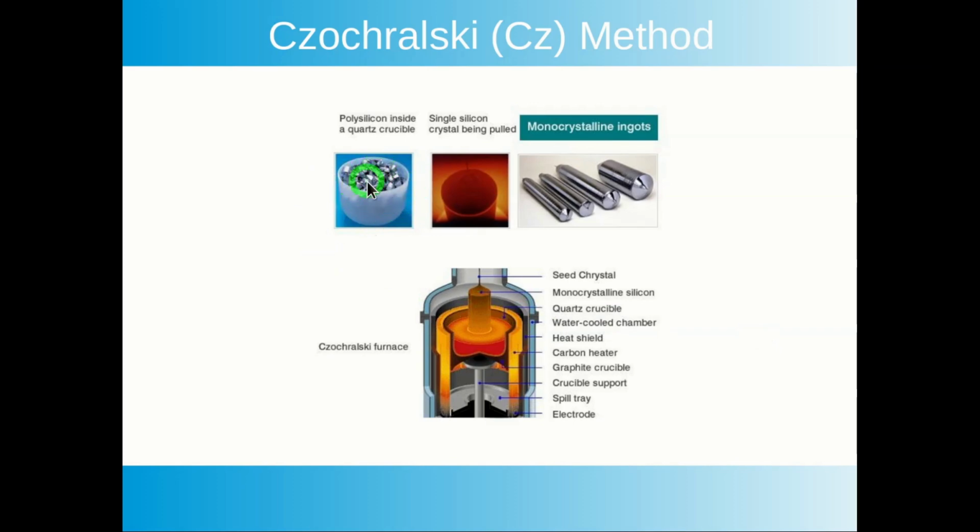solid metal grade silicon inside, and when they pull it out with the seed crystal, what ends up is at least 99.999% pure silicon, which is this ingot, and it can be up to 6 to 8 nines depending on the requirement. For solar modules, or solar cells, it is around 5 nines, but for semiconductors, it is around 6 to 8 nines. So that is how these pure silicon ingots are created for monocrystalline solar cells.